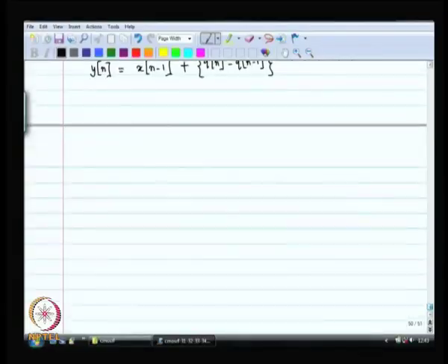You will find that z inverse x is actually an all pass transfer function, it passes everything, it is just the previous sample of x, right, and 1 minus z inverse is a high pass function. If there is a change in quantization noise, then it is going to go through. If there is no change, it will not go through. Okay. So, let us do an example.